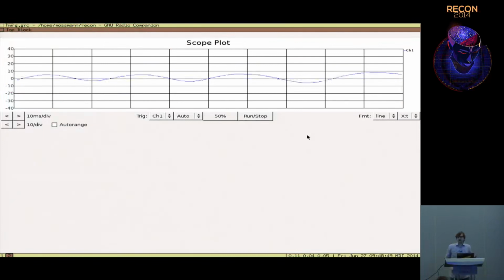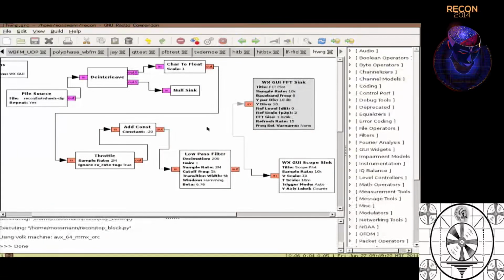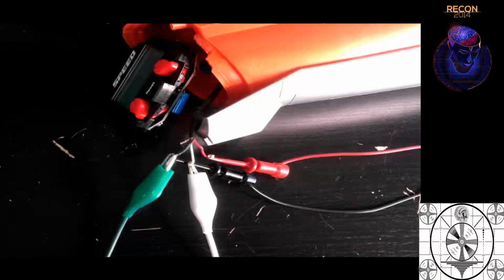And so what I did was I just tapped into the Hot Wheels radar gun, plugged it into the direct ADC lines and baseband header on my HackRF, applied power to the Hot Wheels radar gun, and waved my hand around in front of it. And this is the resulting signal that I get. Pretty cool, pretty useful as just kind of a general purpose oscilloscope, as long as you understand the limitations of what you can plug into it and how that signal has to be conditioned, perhaps. But in this case, I was able to just plug directly in and visualize that signal.